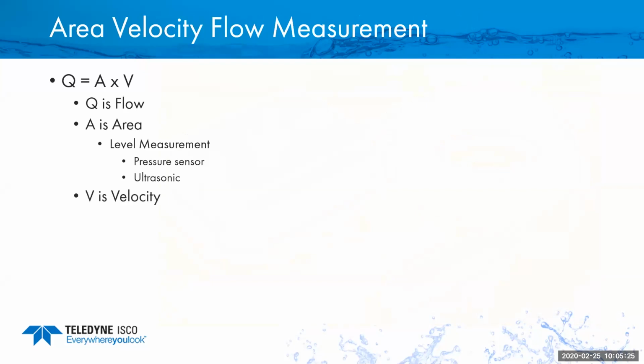Once we know the area, we need to know the velocity. V is our velocity component. It's a Doppler technology or technique. We can either do a contact, which means I have a sensor on a ring in the water, or non-contact in the case of the laser. So we'll talk a little bit about both of those.